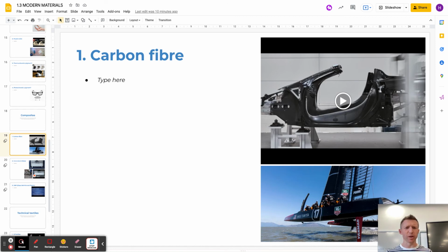Another reason why it's terrible for any kind of regular everyday applications is because it's really hard to repair. If you crashed a McLaren, not even badly, but enough to cause, say, dents on a regular car, what happens is carbon fiber doesn't dent. It will very slightly bend, and then it'll suddenly snap and crack.